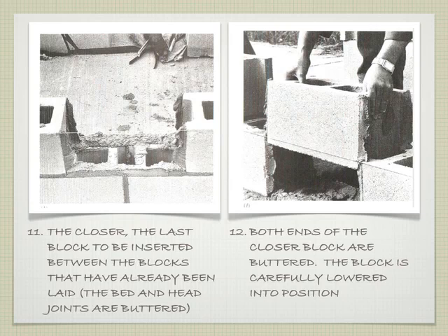So what they do is put the mortar inside this hole for the closer, and they also put it on the outside of this block to be dropped in. That's to make sure that we're being redundant. Even though we end up with a little bit of extra mortar, we want to make sure that it has plenty to tie the whole wall together.